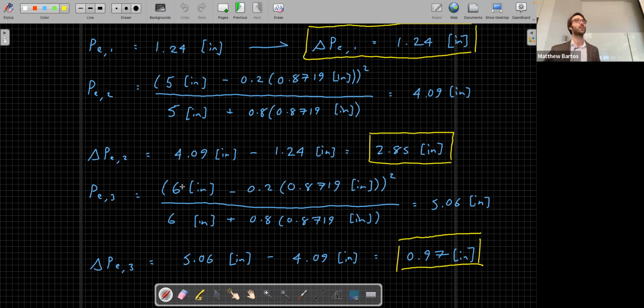So keep this in mind when using the SCS method. It uses the cumulative precipitation over a storm event, which implies it's not suitable for continuous simulation. It has to be reset after every storm event. Are there any questions on the curve number method? Great.